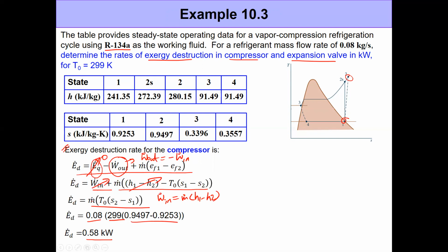So here we have not calculated the exergy destruction for an expansion valve, but in general, you should know that the largest exergy destruction occurs in the compressor when we talk about the vapor compression cycle. If it's happening in any other component, then that's something that you can figure out and reduce in an economic manner.